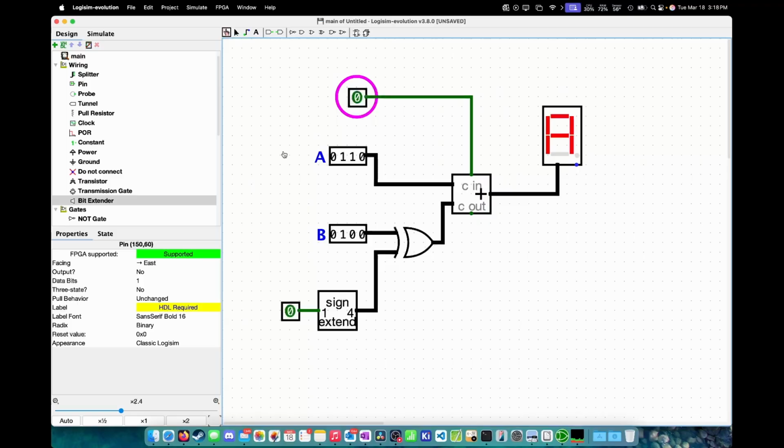Now the process of subtracting is basically the same as before, but now we have something in place to automatically invert the subtrahend. Same as before, I'm going to say we want to take 6 and subtract 4 from it. So we're going to select this bit right here, which will invert this subtrahend, and then click on here to add 1. And we have our 6 minus 4 equals 2.